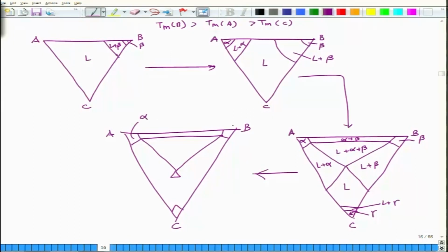So let's say this is alpha, this is beta, this is gamma, and alpha plus gamma make a phase field, alpha plus beta make a tiny phase, beta plus gamma make a tiny one. So this is alpha plus beta, this is alpha plus gamma. Here you can have beta plus gamma, and this tiny area is nothing but liquid. And then in between you will have, sorry, liquid plus gamma, and in between you will have two phase fields.